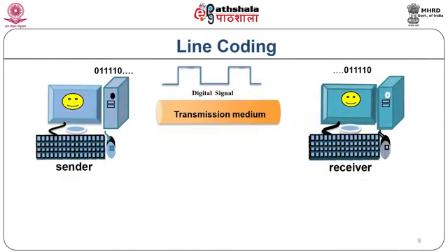Long distance serial transmission of data over coaxial cables, optical fiber or RF link requires suitable encoding of binary data so that the logic states high and low in the signal can be detected appropriately. Also, the signal during transmission through any type of communication channel, wired or wireless, suffers from attenuation and distortion, which is more severe in a long-haul data transmission channel.